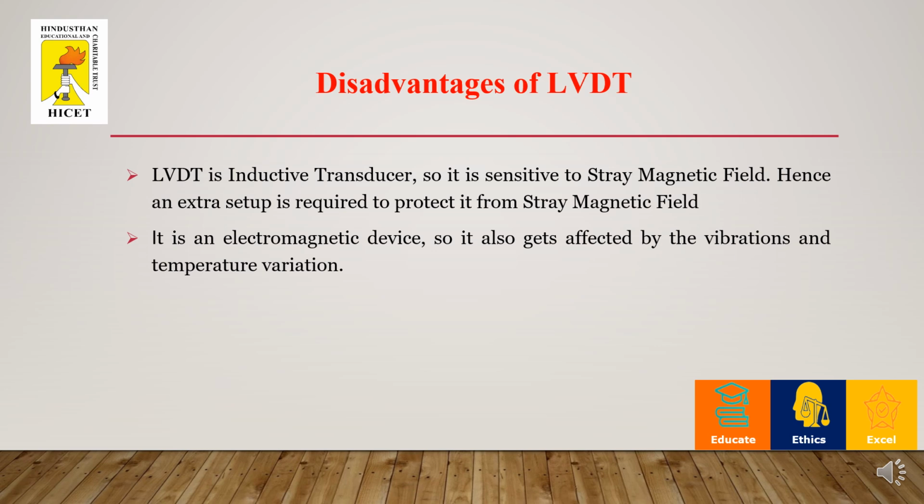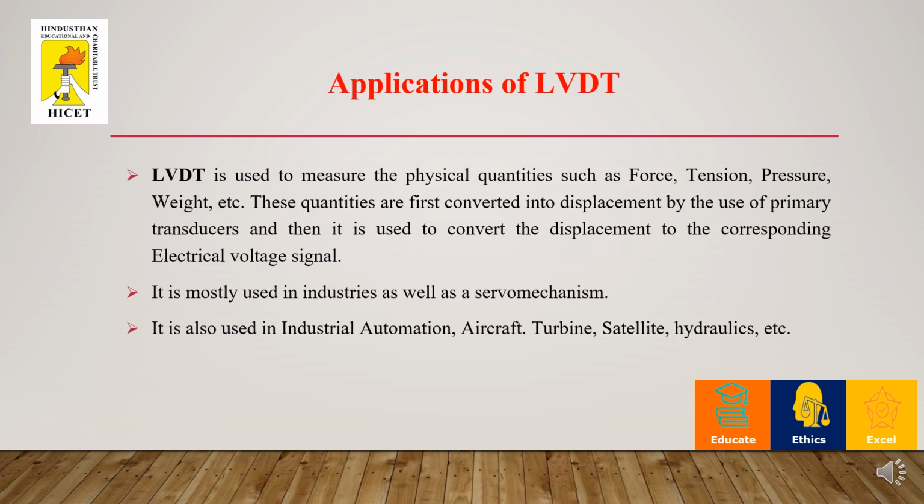Whenever you have a stray magnetic field, that is an extra magnetic flux being induced in the LVDT, the total system is going to collapse. So it's an electromagnetic device. Whenever it is affected by any kind of vibrations or temperatures, definitely it is going to affect the performance.